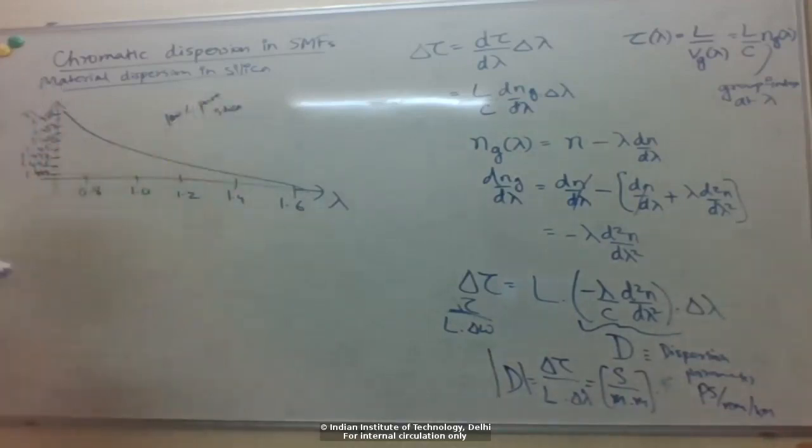So for optical fibers, we sometimes also dope the glass with some other atoms to change the refractive index. Okay, so for example, we need some index difference between the core and cladding. Right? So for example, we dope the core region with some material to increase the refractive index slightly. So that will change this by a very, very small amount, right? Again, the deltas we were talking about were 10 to the minus 3, 10 to the minus 2, remember.